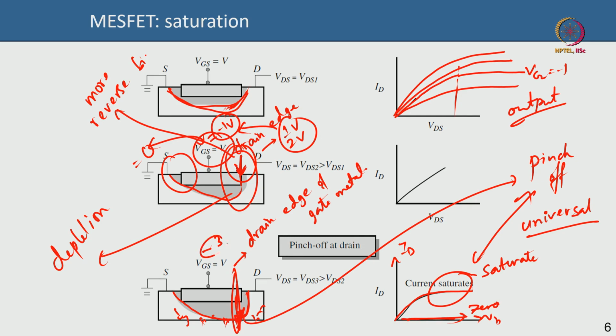However, if the gate voltage is, as I said, not minus 3 volt but suppose 0 volt, and the channel pinches off here, the current will saturate, the current will be high, this could be say 20-30 milliamps. The transistor is not off, the current just saturates here. And that is very remarkable because the channel thickness has been reduced to 0 by the gate, but because the drain voltage is higher than a certain threshold enabling pinch off, the device current actually saturates.